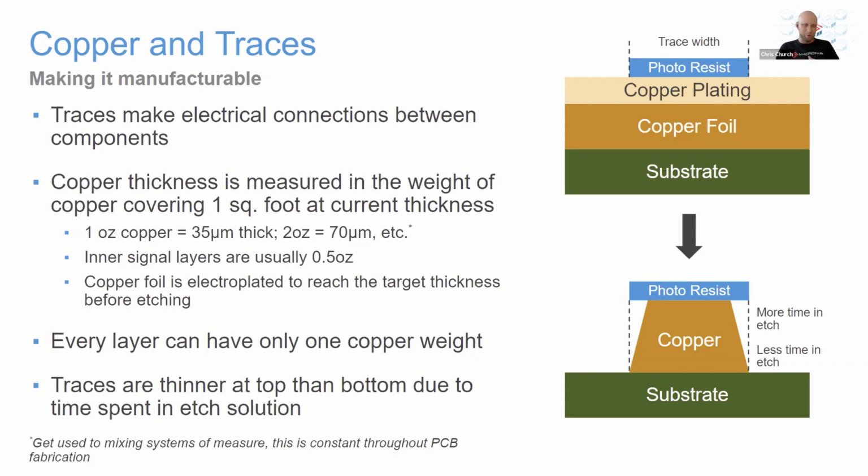And that's how some places can do very, very thick copper, because they have thicker core on hand and a process that can run longer in that electroplating without damaging the device. If you look on the right here, there is a little diagram. When we're designing a board, we think of our traces as perfectly rectangular, right?